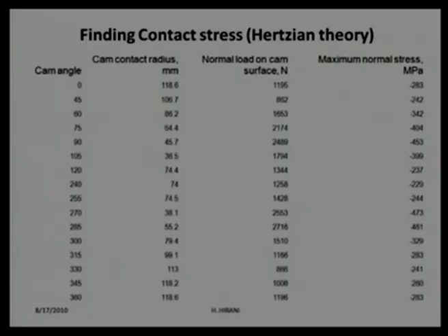Now, if I go ahead with Hertz contact stress theory, instead of 25, I have used a few divisions so that it can be accommodated in one slide, and we have figured out the cam contact radius everywhere. The follower contact radius is always constant. We are assuming that wear on the follower surface is negligible compared to the follower radius, and the normal load on the surface has been estimated based on the force geometry.